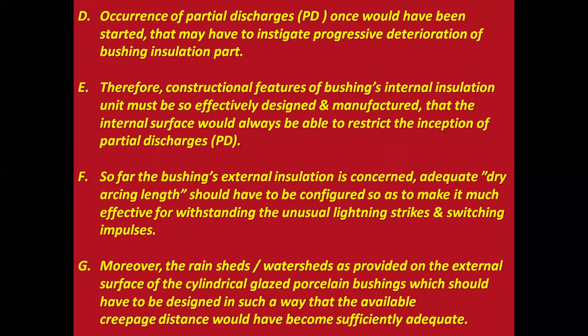D. Once partial discharges have started, they may instigate progressive deterioration of the bushing insulation part. E. Therefore, constructional features of the bushing's internal insulation unit must be so effectively designed and manufactured that the internal surface would always be able to restrict the inception of partial discharges.